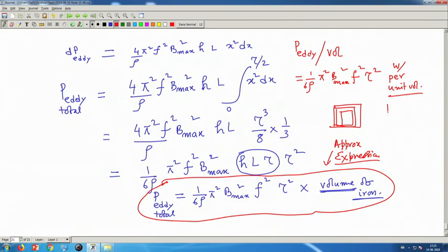Instead of that, you use thin plates, and the eddy currents will be confined only here, because the next plate is insulated from the other. If you do not use insulated plates, then the story remains the same, the eddy paths will be more. Are you getting? That is why the insulation is necessary.